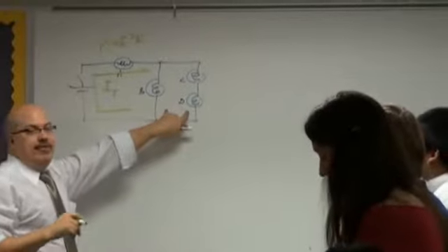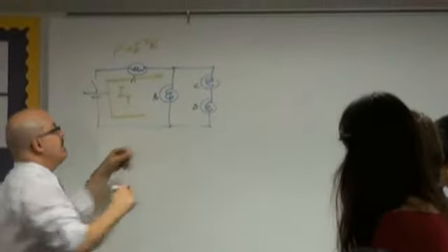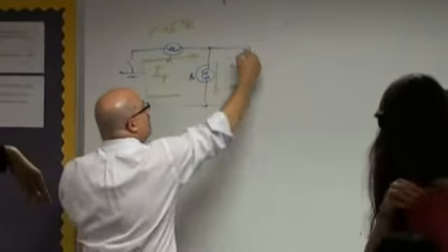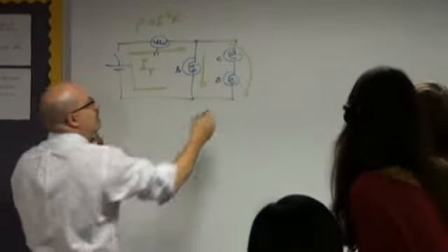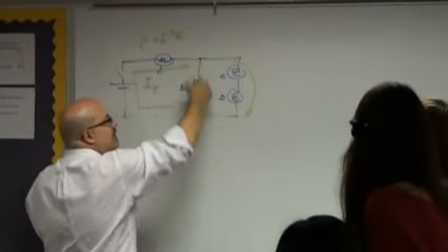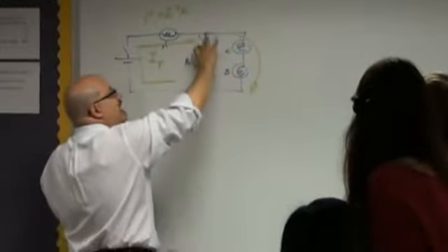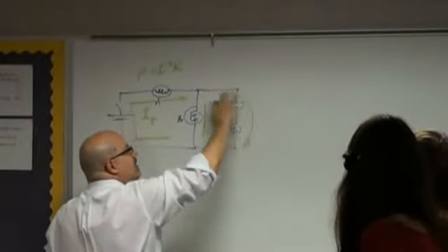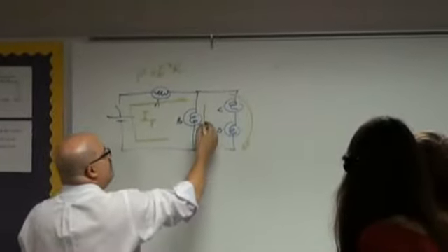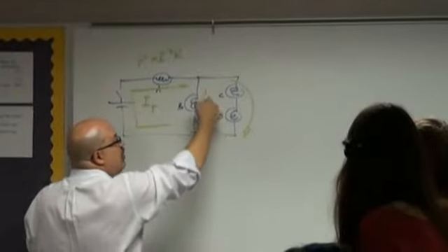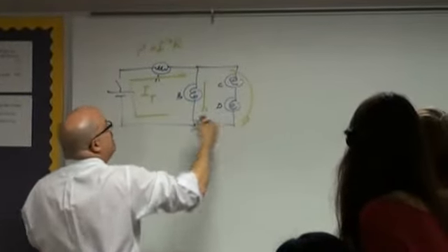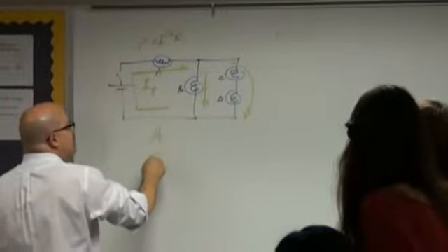Okay, now, what about these? There could be more current through B. Why more current through B? Less resistance. We have less resistance in this line than this line, and they have the exact same voltage difference here and here, right? So the current through B should be bigger than the current through here. So A should be the brightest, B should be next.